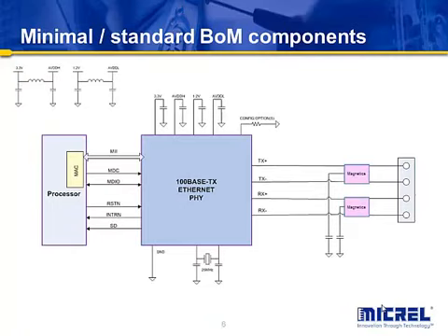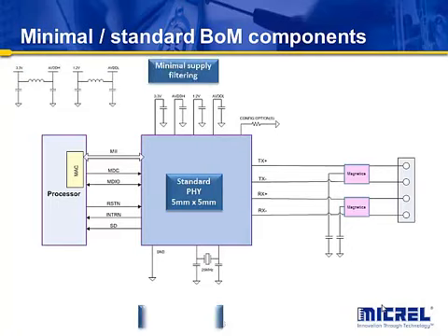The Ethernet circuit diagram is relatively simple. The host processor is connected to the PHY via a standard MII digital interface. But here the key is that the PHY is a standard Ethernet device that is used for other applications as well, from, for example, industrial control to consumer. This provides high volume usage and reduces costs. A 100 ppm crystal or clock source is used to be standards compliant. However, in reality, available silicon can operate at a much wider range. Automotive can take advantage of this and reduce costs further by utilizing a lower accuracy crystal.